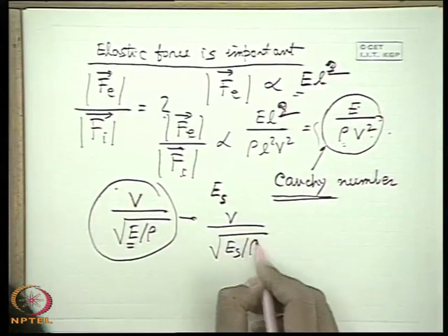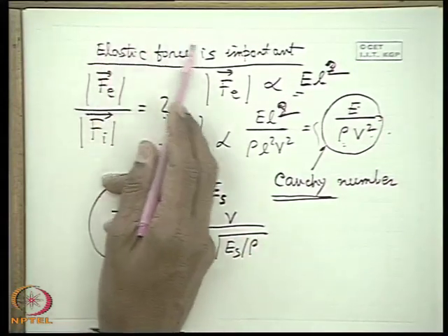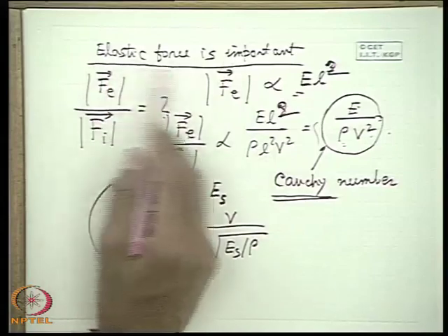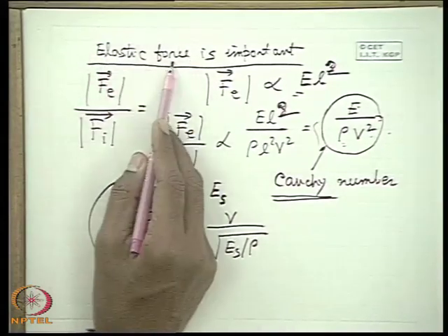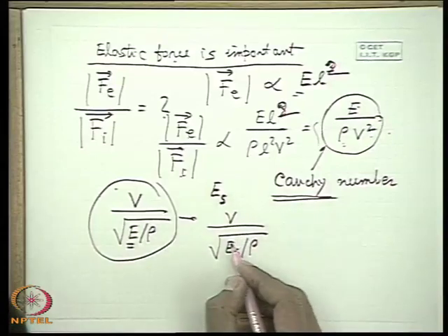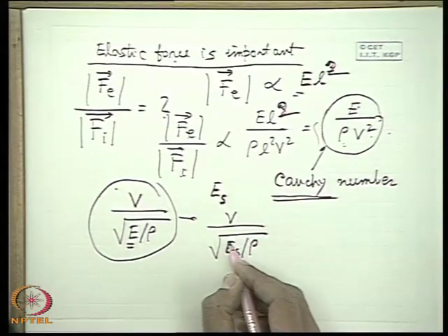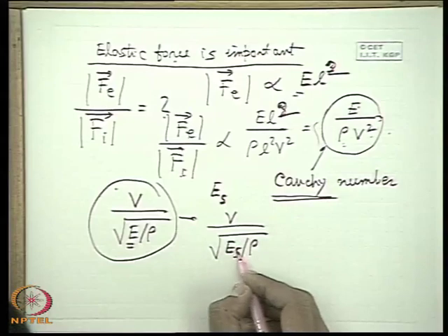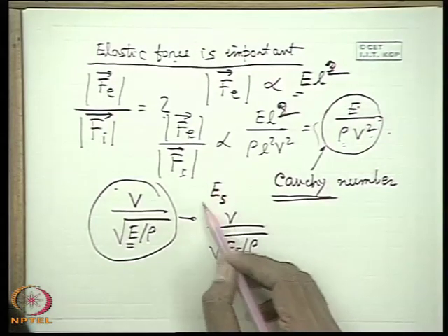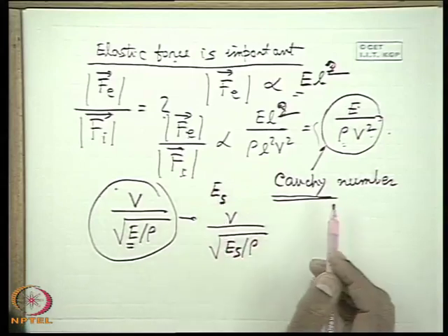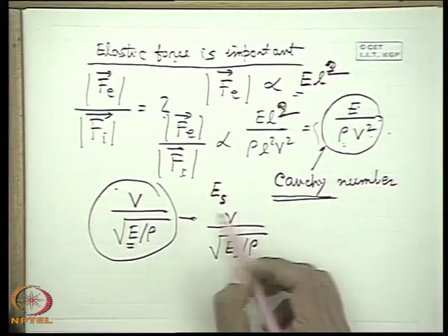And exactly for the flow situation where elastic force is important, the flow is so fast, the velocity is so high that the elastic force becomes important and compressibility comes into consideration. Any change in the density or volume due to pressure is considered very fast, and so this is considered to be adiabatic. Thermodynamically a fast process means an adiabatic process because there is no time for heat to be